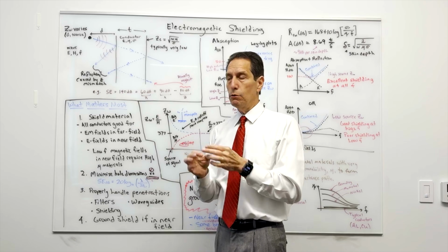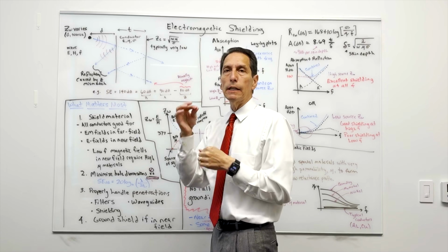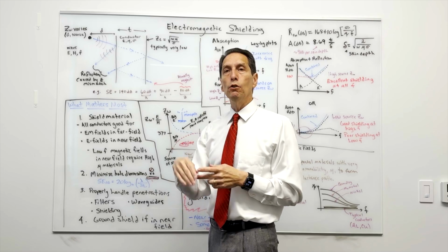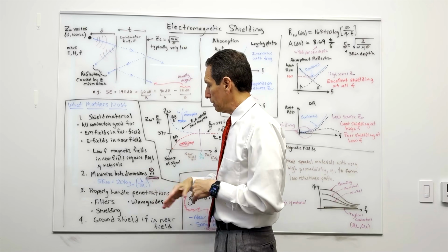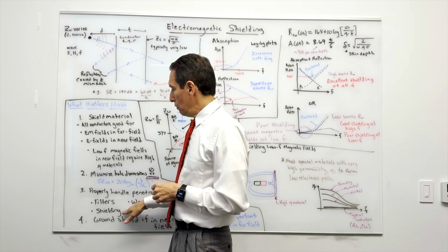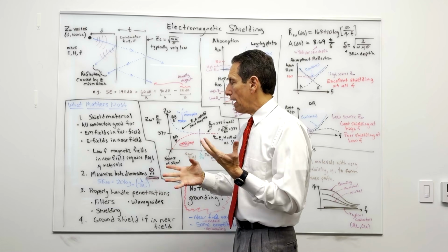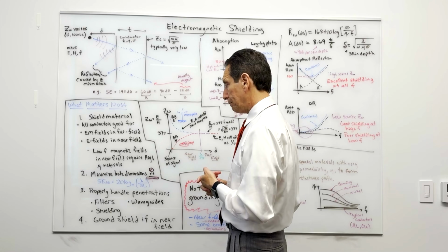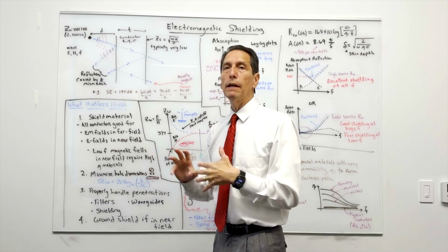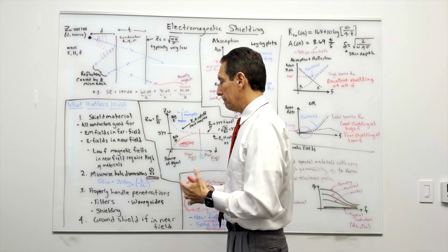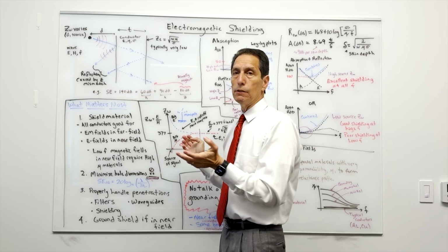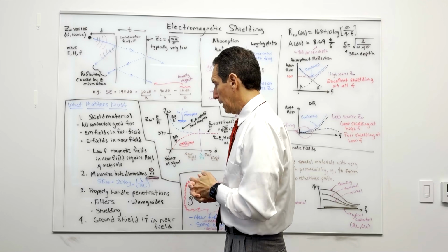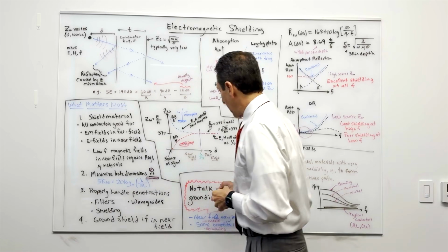Waveguides, if you're having to pass, let's say, fluids or air into the box, you can use special waveguides, which are just long tubes that are specially calculated in length and diameter that will not let the incident energy come through the tube. It just gets attenuated as it tries to go through the tube. And you can use any kind of ferrites or shielding on the penetrations as well. All right, so you have to handle the penetrations properly. That's the short answer of it. Or you can really compromise your shield and all of the work was for nothing if you end up not paying attention to penetrations.